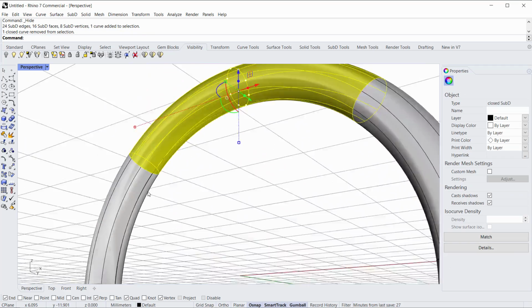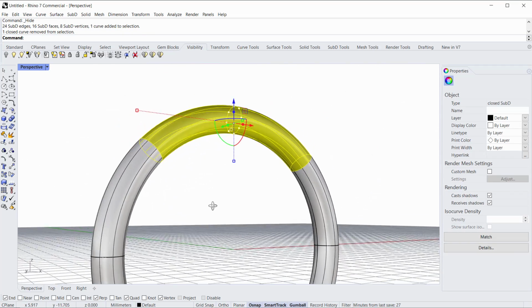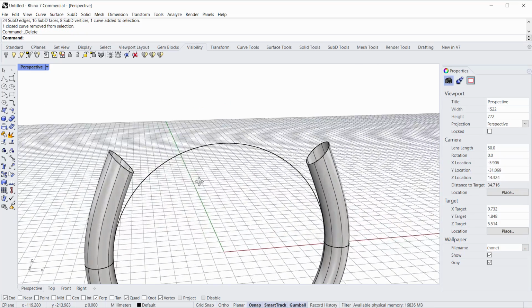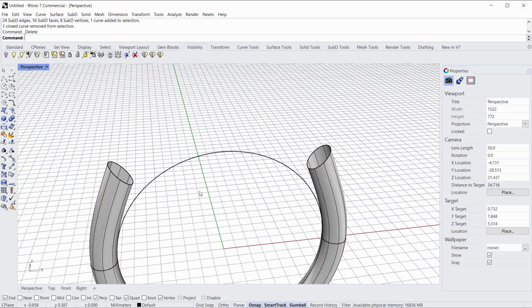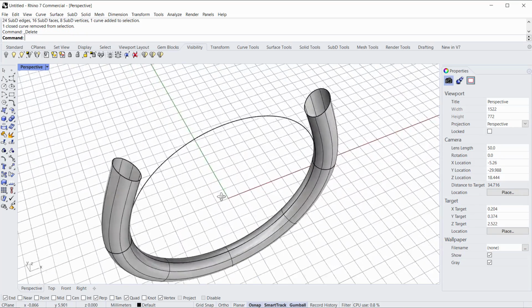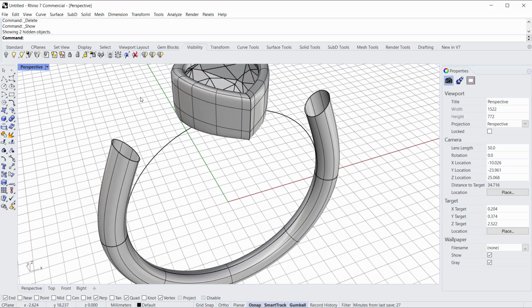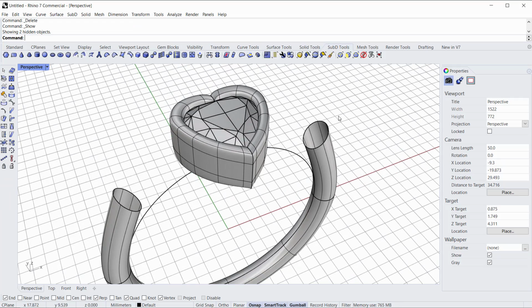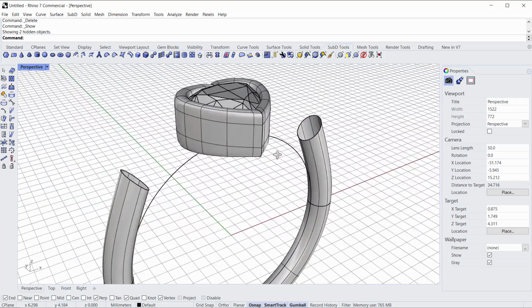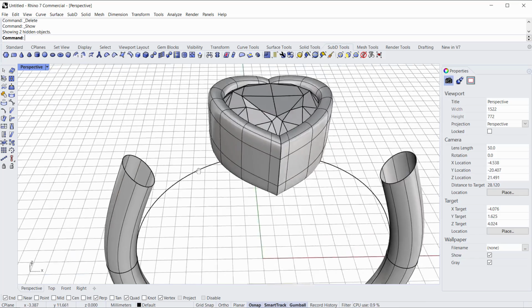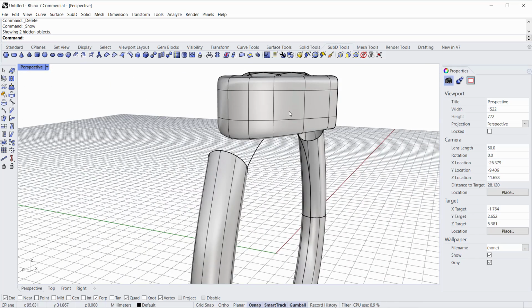I don't want to take our finger curve with us there. So I held Control and deselected that from the selection. So now I pressed delete on the keyboard and deleted those faces. And so now the shank opens up. So we'll turn the lights back on here and let's go over to SubD tools. And now what I want to do is I want to blend all this together, right? I want to bridge that into that.